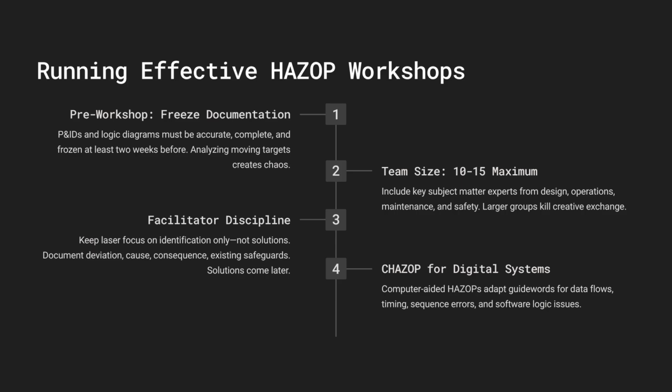And one more thing, with so much digital control now, we often run computer HAZOPs. Same principle, but the guide words are adapted to focus specifically on data flows, timing, sequence errors, data corruption, software logic issues.